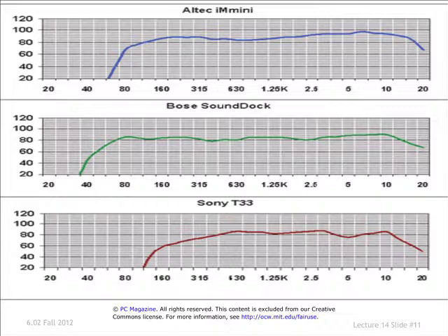So for this particular one, you would hope that the spectral content of what you're trying to send through the channel lives somewhere in maybe 300 hertz to 10 kilohertz if you want to get it across the channel, from the speaker with high fidelity. But if you've got a low frequency signal that you're trying to send and you use the speaker, well, you're going to be out of luck. It's not going to propagate it very well. Okay? So thinking in terms of frequency response and spectral content is really key to making sense of a lot of this.